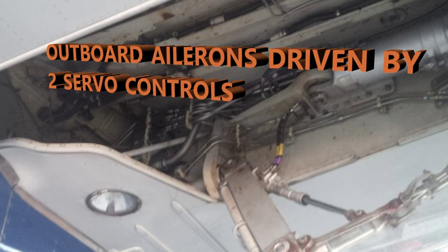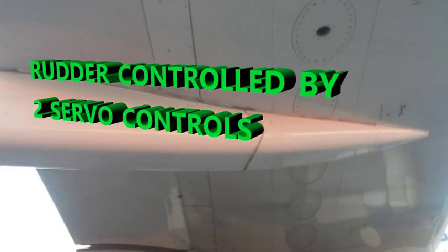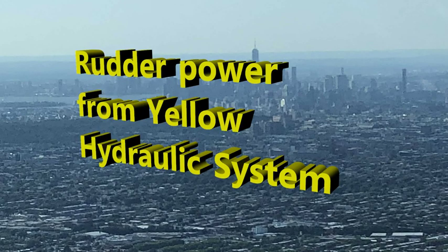And the other one that has 2 conventional servo controls is the rudder. So for rudder control, there are 2 servo controls there. Remember, what they're doing is just sharing the load, just so that it's dealing with the stresses of the material of the aircraft. And just to note, with the rudder, the hydraulic power is coming from the yellow hydraulic system.